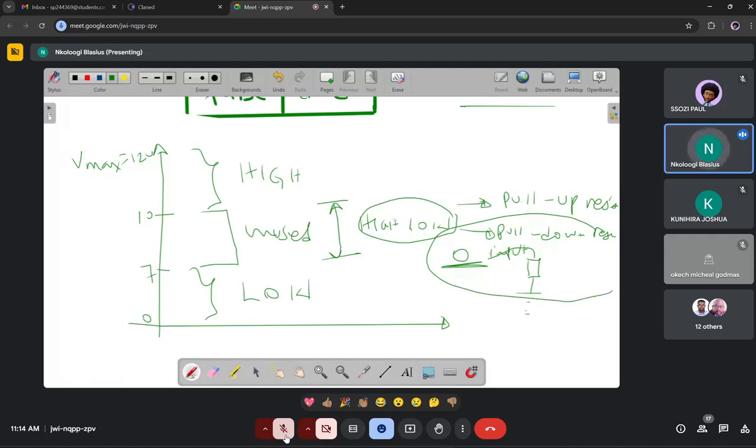On the other hand, if you're using a pull up resistor, you are by default trying to set that input line to be high or to have a signal of 1. And in that case, you will only connect a resistor which is coming to the input of your circuit, and this resistor will be connected to the voltage which is already up, because with a circuit you always have two wires.